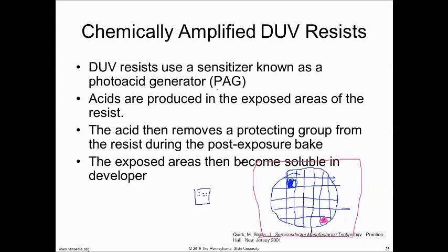What a stepper is, I'm not going to have a big mask like this. I'm going to have a mask, and my mask is not going to do all the dies on the wafer. It's going to do just one Pentium chip. Does that make sense? So now what I'm going to do with that, and I'm going to switch my colors again as if it makes a difference, I'm going to go to green or something. Now I'm going to apply this die, and I'm just going to write this one right here.